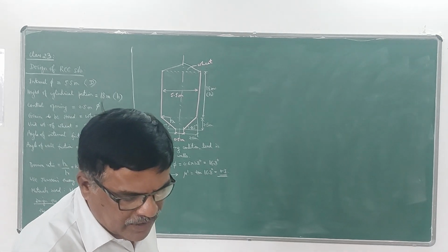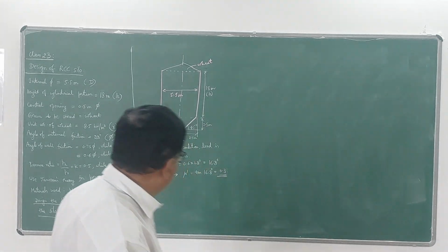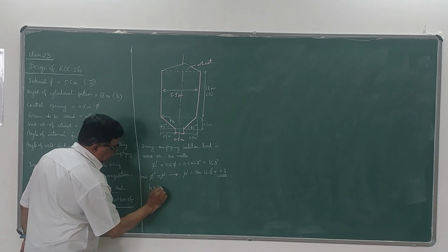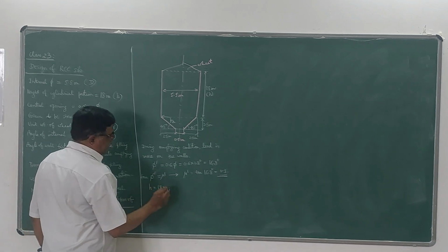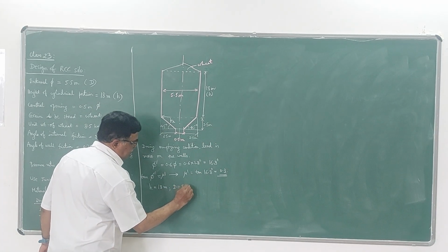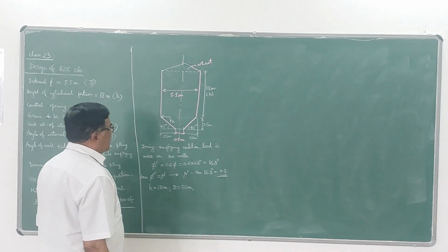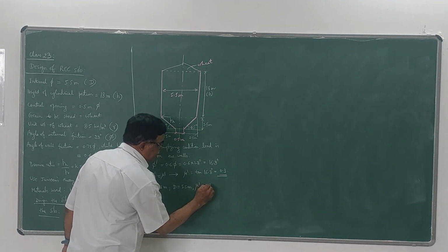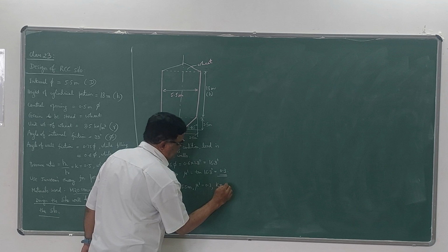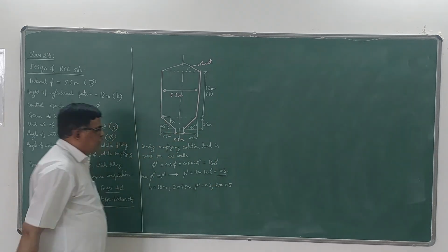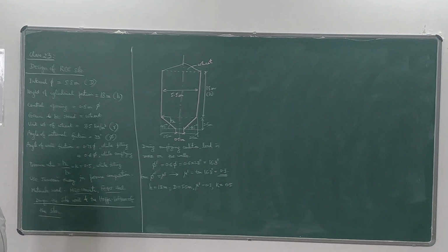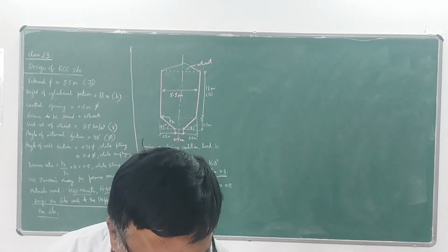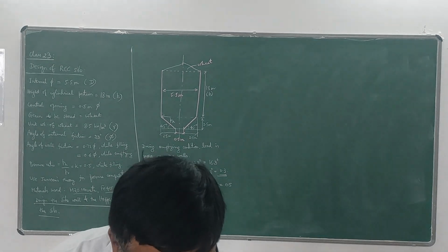Now we have to find the horizontal pressure pH at this level. For that I have to take H equal to 18 meter, that is given. D is 5.5 meters, diameter of the cylindrical portion. Then mu dash as 0.3, and K value, of course, he has given pressure ratio 0.5. So these are the values I need now. Now I will write the equation for getting the value of pH using Johnson's theory.